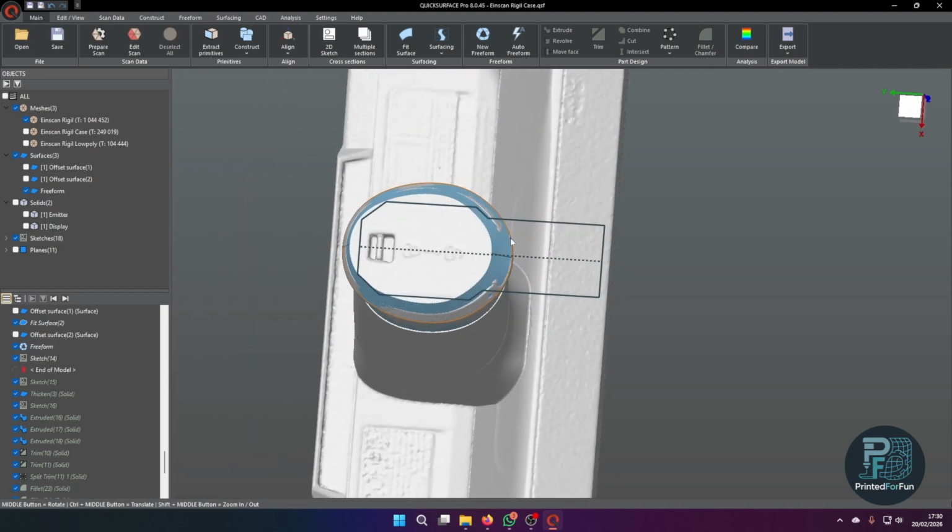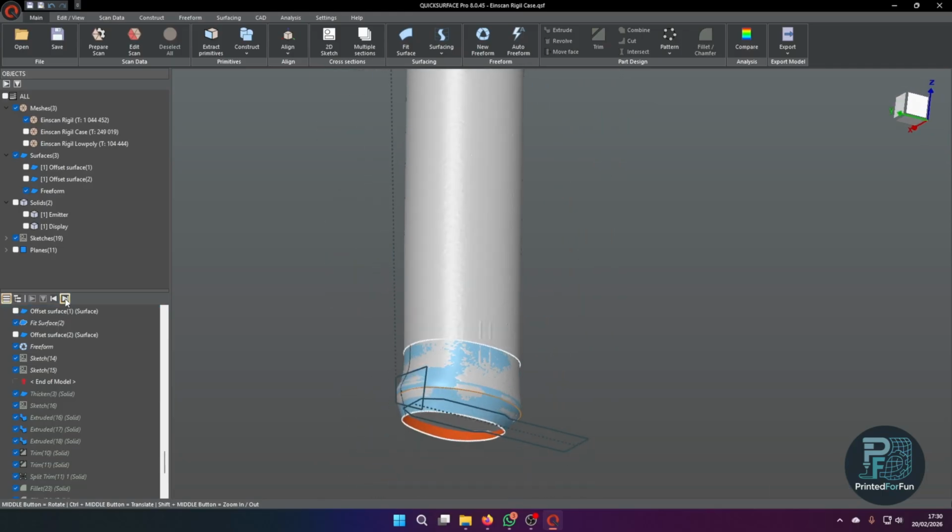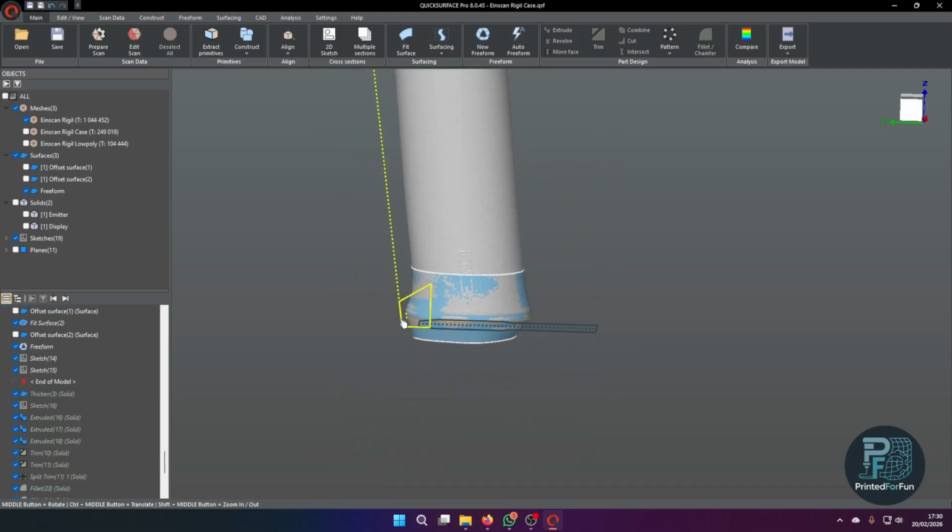Then I created a sketch for the cutout of the battery latch, or of the battery cover. So originally it uses two cylindrical batteries, and they are behind the small hatch. It folds open a bit like on a regular camera. So I had to keep the space clear here. And I also wanted a lip to the front where this bottom part can rest on.